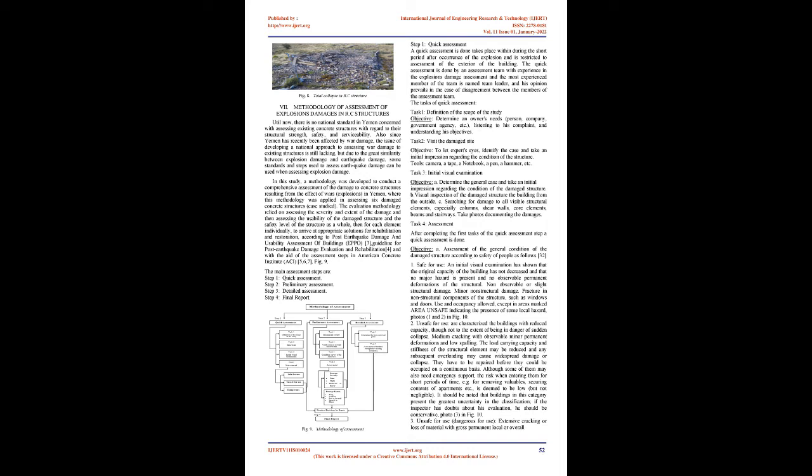The evaluation methodology relied on assessing the severity and extent of the damage and then assessing the usability of the damaged structure and the safety level of the structure as a whole, then for each element individually, to arrive at appropriate solutions for rehabilitation and restoration, according to Post-Earthquake Damage and Usability Assessment of Buildings, EPPO, and Guideline for Post-Earthquake Damage Evaluation and Rehabilitation, and with the aid of the assessment steps in the American Concrete Institute, ACI, 5, 6, 7. Fig. 9.